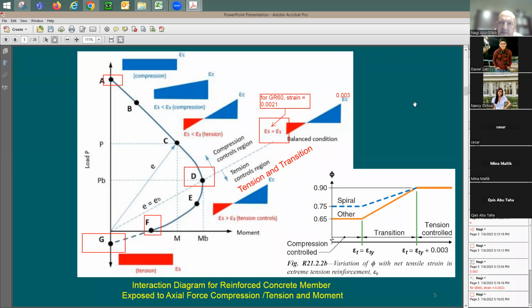The points of interest that I care about when it comes to, let's say, a midterm or maybe a final are going to be these boxed points. Axial compression, yeah. Balanced point, yeah. And it's going to be a simple one to do the analysis for. Because when the strain here is going to be 0.0021 and the strain here is going to be 0.003, finding the neutral axis depth is going to be an easy step. Not that tough. This point here is like beams. We have done beams. This point here is much easier than beams. It's just As times Fy times the phi factor of 0.9.